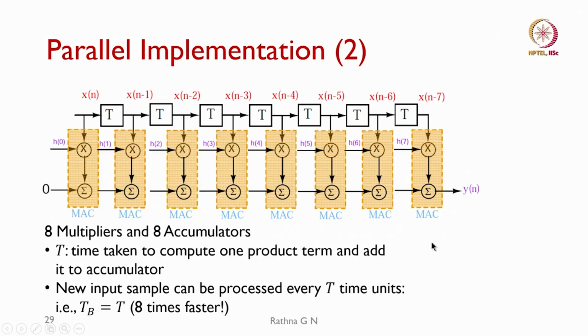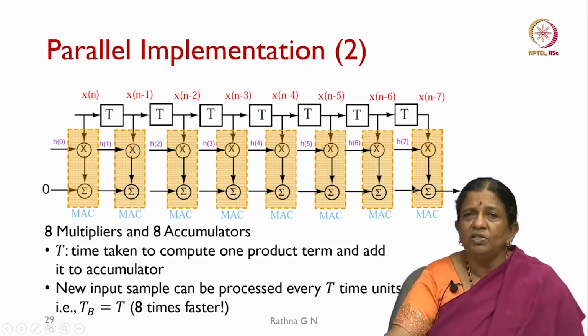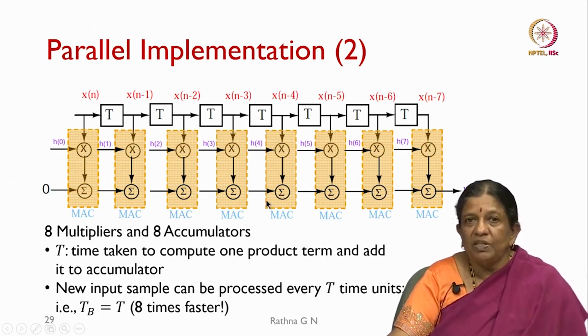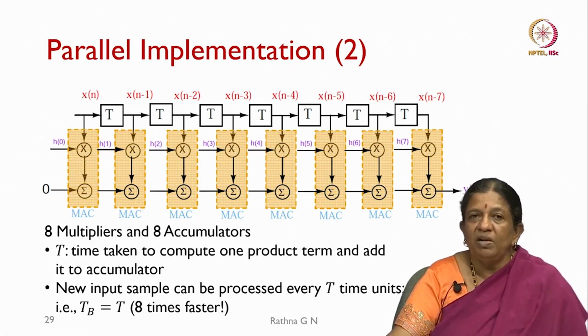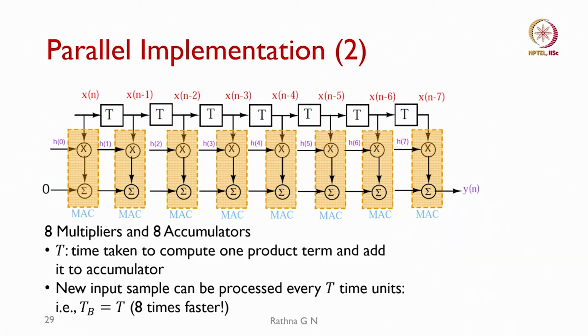So, we will see that instead of 2 MAC units, for each multiplication I know what my filter length should be. Most of you know that in FPGAs multiple DSP blocks are there, and even in GPUs, for that matter, you have multiple multiplication and add units. That is how you get your speed up using GPUs compared to your CPUs. So, here I have used 8 MACs in this case. 0 will be pushed into the first adder, and the rest can be fed from the previous stages.